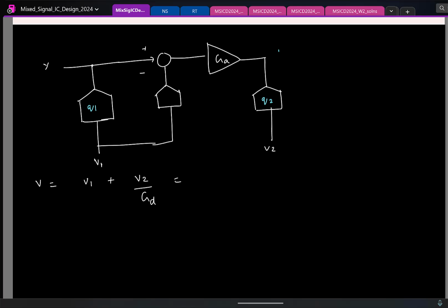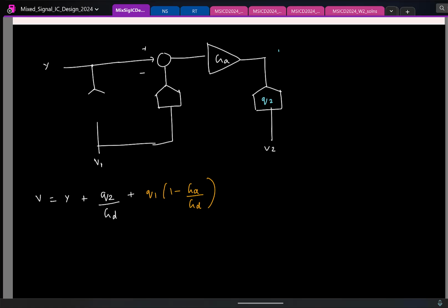So you have basically the desired signal plus the quantization noise from the previous stage that appears with this factor. Okay. So I'll also get rid of this to make space. So this is the final output. And I know that the first ADC can be modeled as the additive quantization noise. Fine.